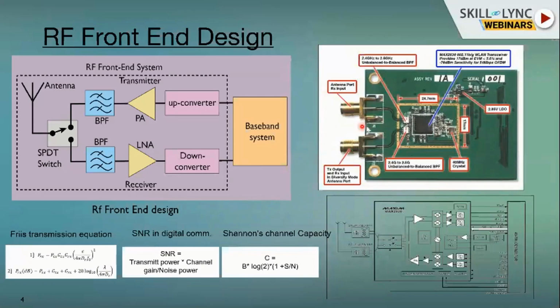You can see here one of the ports is written as an antenna port. Here the antenna is not yet joined. This is in the PCB. This will be your RX input and this is the TX output, right? They are called coaxial connectors, and they join to the total transceiver system. This is the part that relates to your antenna positions. Here you need to place the 2.4 to 2.5 gigahertz antenna, since this particular board is a Bluetooth transceiver. So the Bluetooth antenna has to be joined.